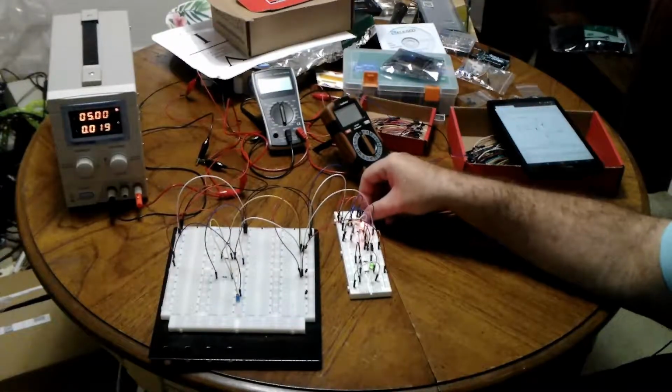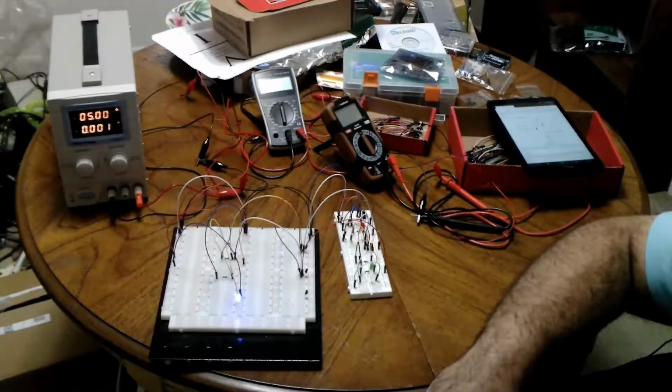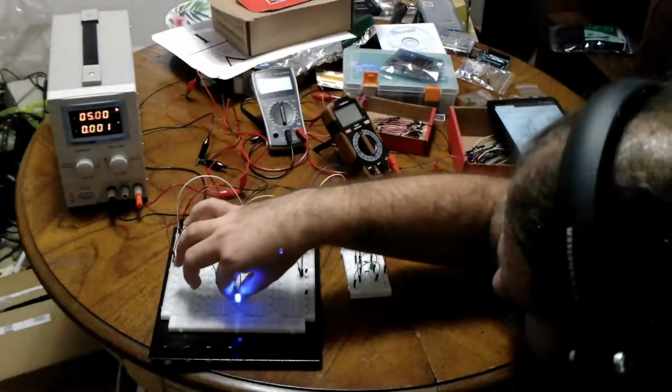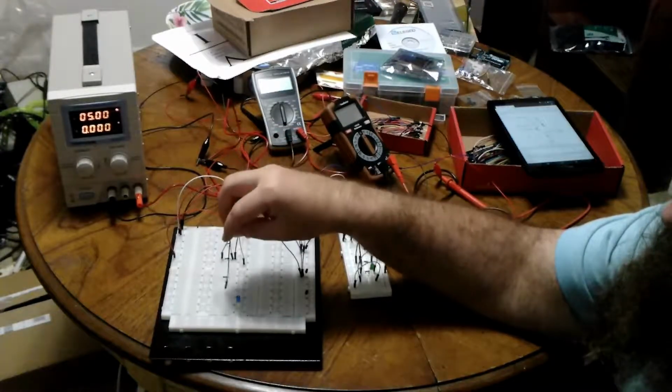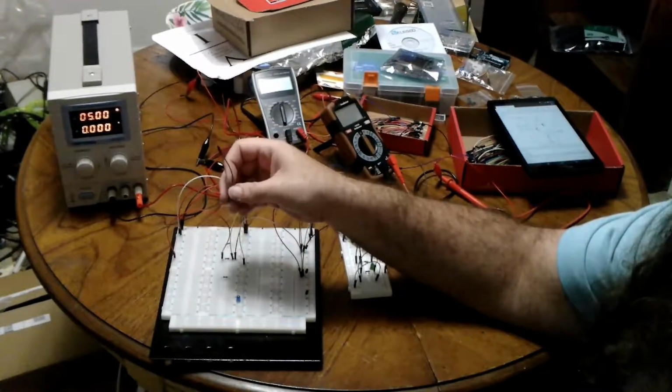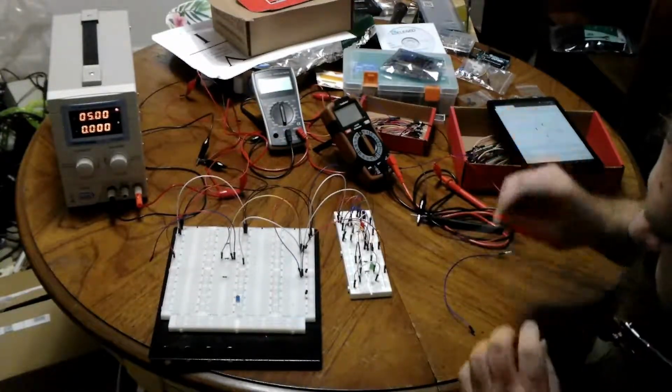So I have a NAND gate, but I wanted an AND gate. So what if I just hook this up through a NOT gate, right? So let's do that. Let's make a NOT gate. Let me unplug this load. So the output of that resistor, instead of going into my load, is the input to my next circuit, my next gate. So let's leave that there.